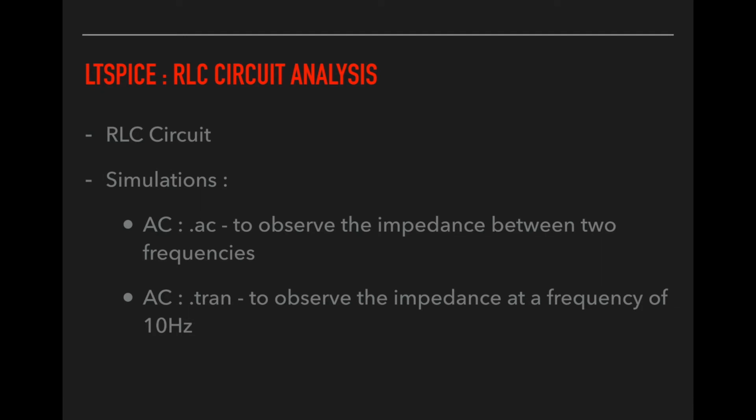Hello and welcome to this video on the RLC circuit analysis. Today we will take an RLC circuit and make two simulations in AC. The first one will be with the directive .AC to observe the impedance between two frequencies. The second one will be with the directive .tran to observe the impedance at a frequency of 10 Hz.